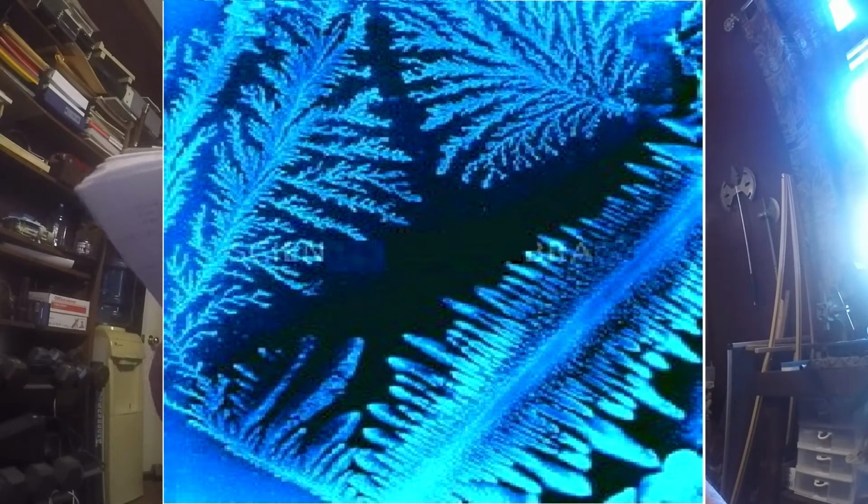This photo serves to illustrate how the dendrites, when done growing, can leave gaps between the crystals, preventing the casting from reaching its maximum strength. Gaps like this can cause a valve or pump body to leak if steps are not taken to counter the defect.